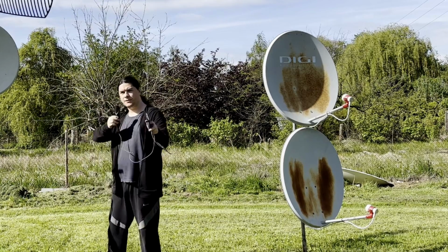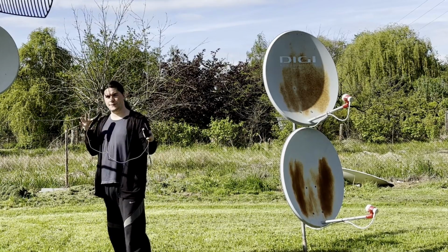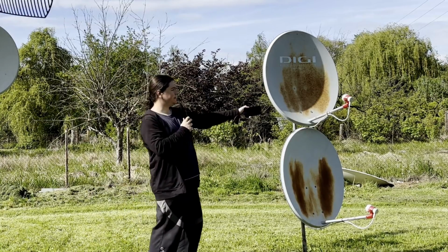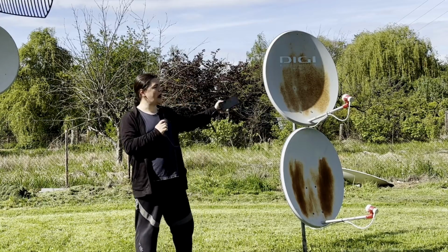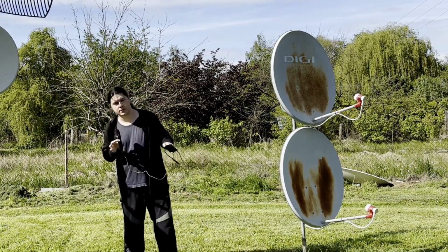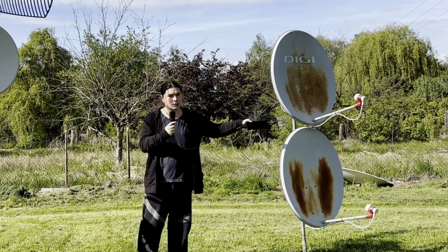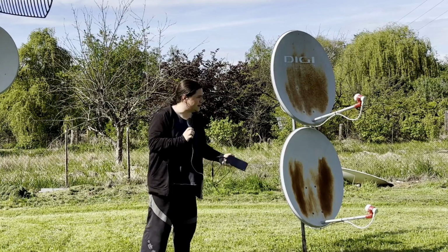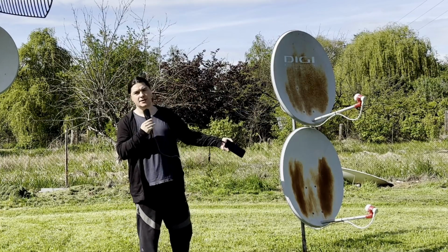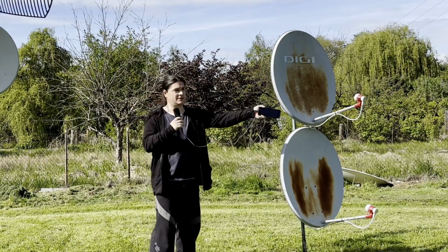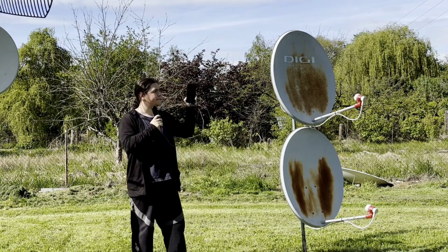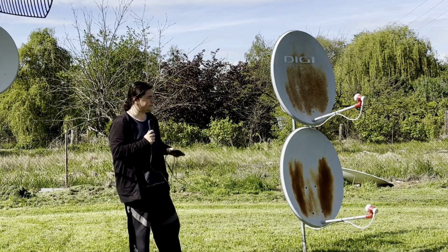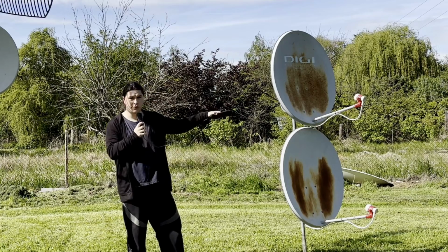Actually, this is one thing that I forgot to talk about that I show in the clips that I recorded. If you have a satellite TV antenna like this already on your house, there are two scenarios. You have it and it's unused, because you have switched to online streaming or terrestrial TV. In that case, you can just re-aim it at QO-100, maybe replace the LNB if it's old, maybe replace the coax if it's old. If you have an antenna like this and it's still actively used for TV reception, you may still be able to use it for QO-100 as well.